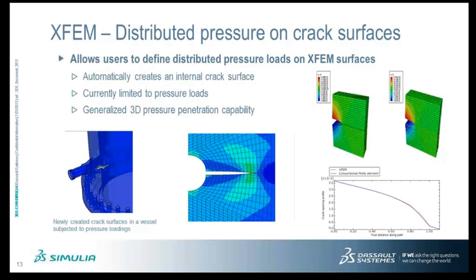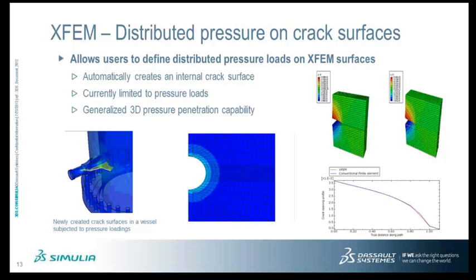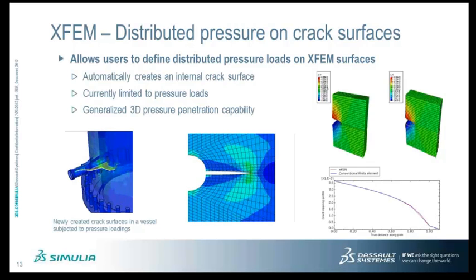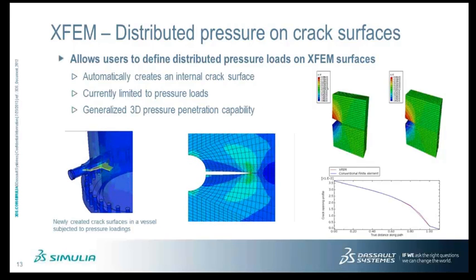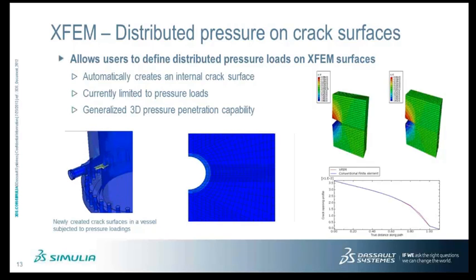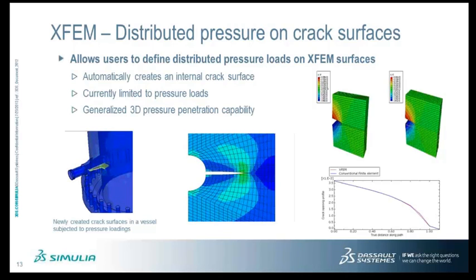In previous versions of Abaqus, we could model fracture, but we couldn't apply any kind of distributed load to these newly created fracture surfaces. In 613, however, we do allow the application of a distributed pressure load to the new XFEM surfaces. So you can see the animation that's running down in the left-hand corner.